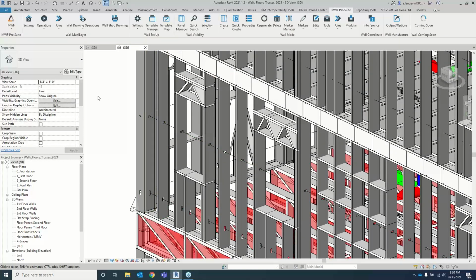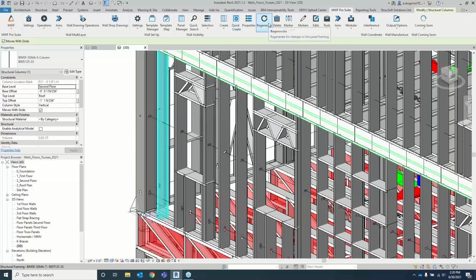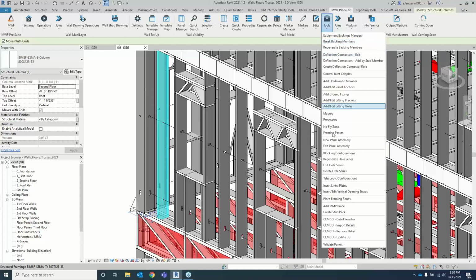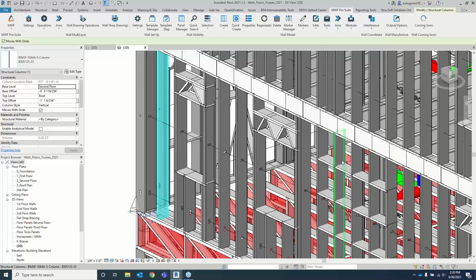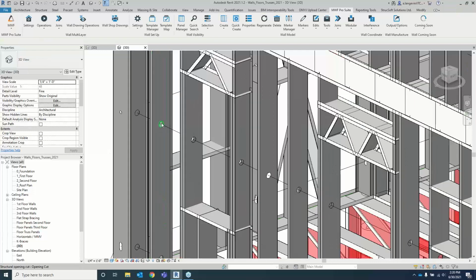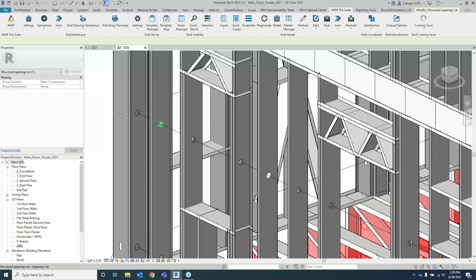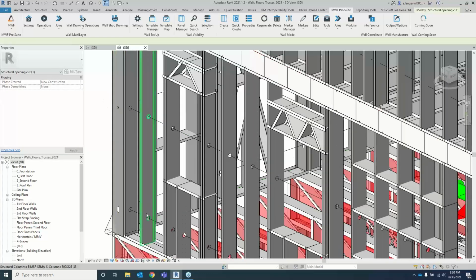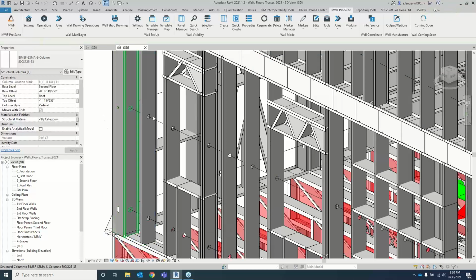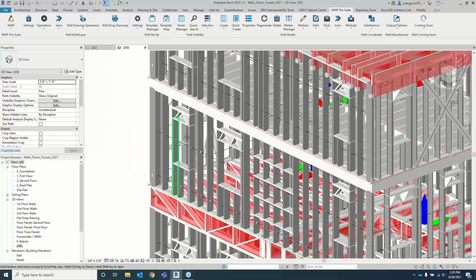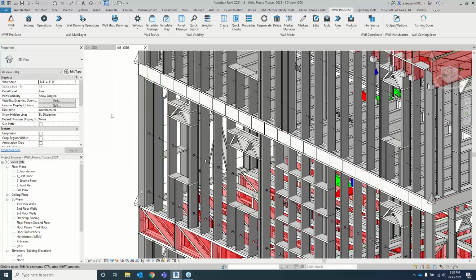Obviously, nothing happens right away. So what we have to do is, again, either regenerate the panel with this tool, or we can just go down here and do regenerate whole series. So if all works well, we'll notice here we got these big 2-inch diameter holes now that have been placed within these 2 marker lines that were created. All right. So those are your 2 options.